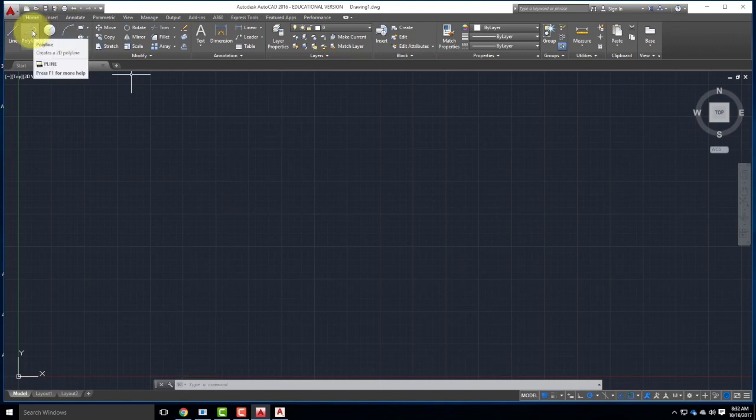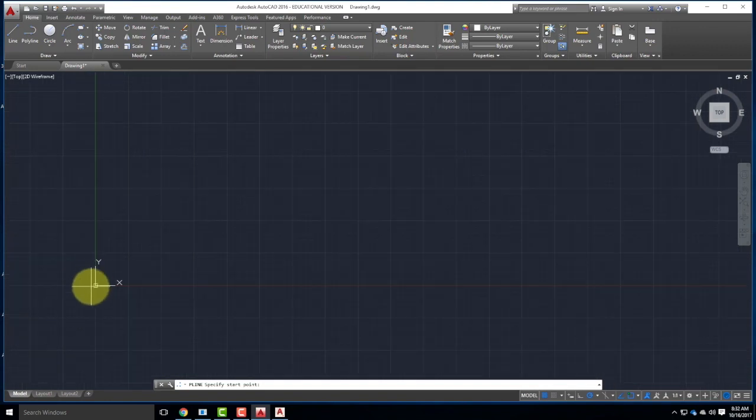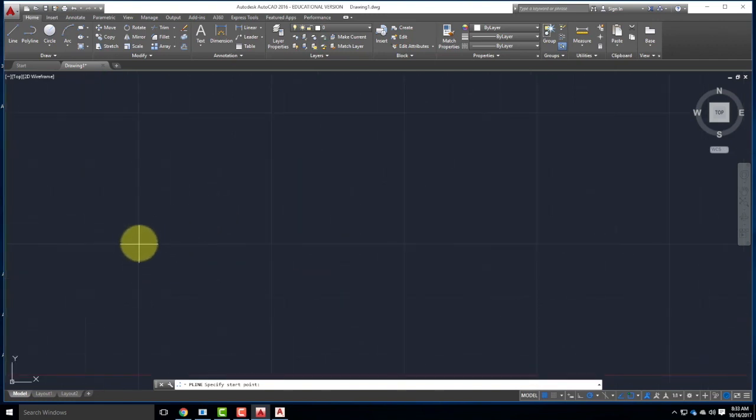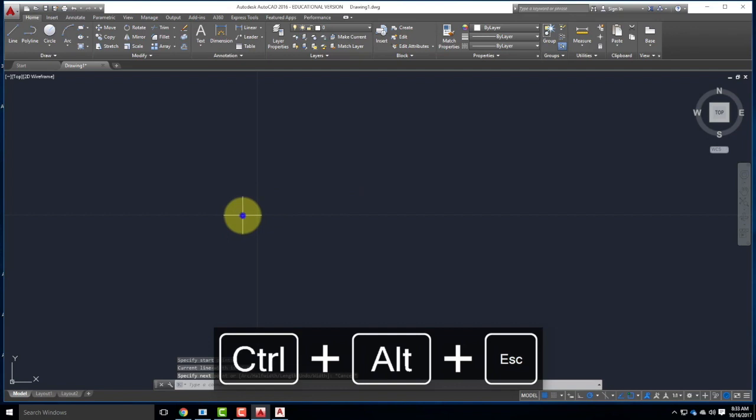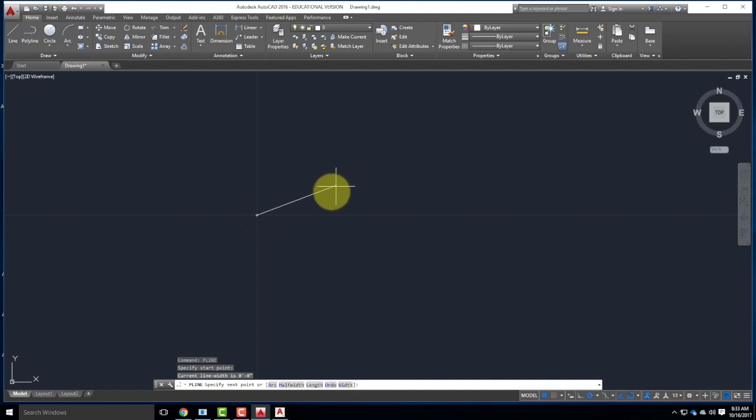I'm going to go ahead and click on the Polyline tool. And as I work in AutoCAD, we know that I want to start at point 0, 0, which is right here. And for illustration purposes, I'm going to do it over here for just a second. Now, let's say that I wanted to put my cursor right where those two cross. If I were to click and say, yeah, that's right on where those two grid lines cross, and oh yeah, that looks pretty good. If I zoom in, you see that suddenly it's not on that cross anymore. That's a problem. So I've zoomed in. Let me try that one more time. I'll get right on top of it. OK, I got it this time, right? Then you zoom in and you're like, well, no, I don't have it.